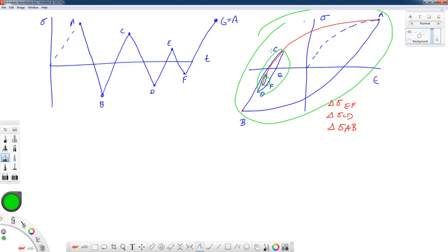If you know the actual material properties, you can even calculate these hysteresis plots. If we use the Ramberg-Osgood equation, and the K and the N, we can go through all of that and figure out the exact values for the stress and strain at each of these tips. Now the interesting thing for rainflow cycle counting is that we never have to calculate strain.